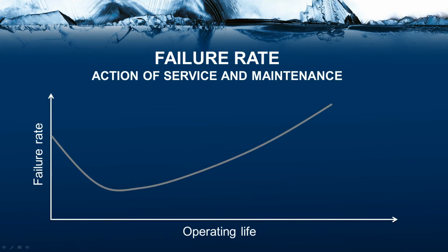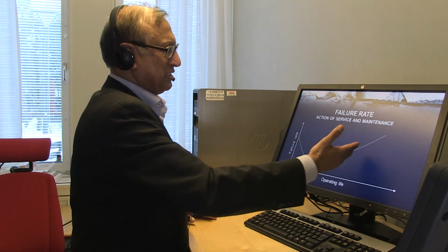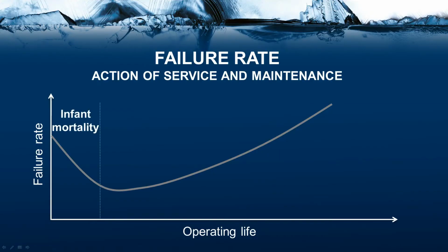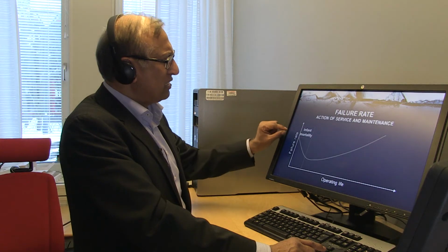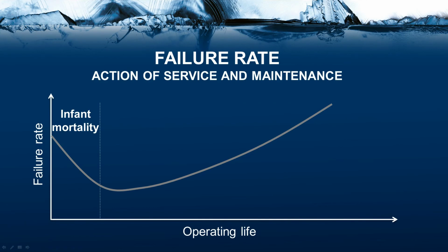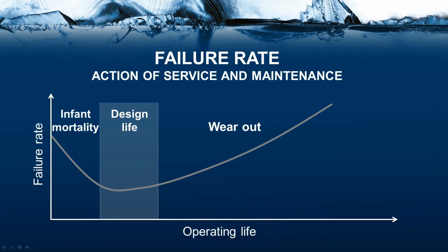Let's look here. This is a normal failure rate of a system with no maintenance. So you will see, this is in the beginning when you bring a system into use. In the beginning it is higher, especially in case of complex industrial plants or complex machines, not your TV, not consumer goods, you don't want this. But most industrial systems, when you commission them, have some failures, what we call teething problems in the beginning, and gradually they become stabilized, and then they start working perfectly, and you have a design life indicated here by this gray zone, and then suddenly this wear out zone starts